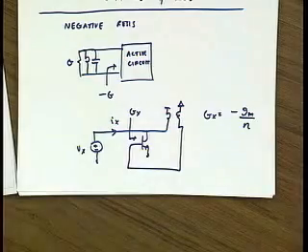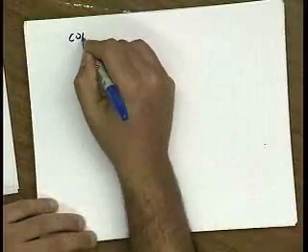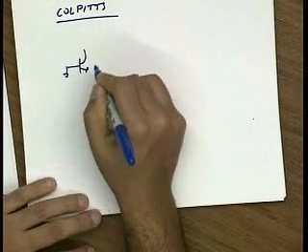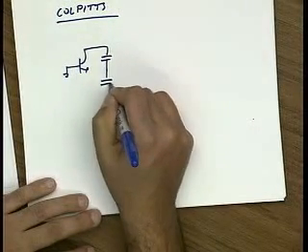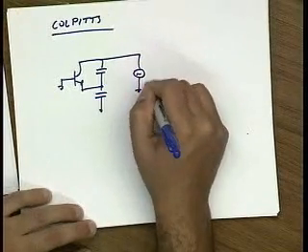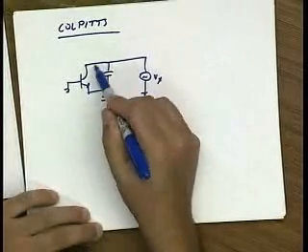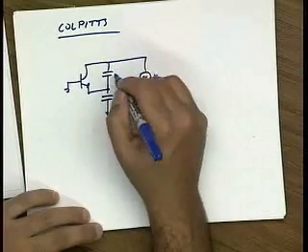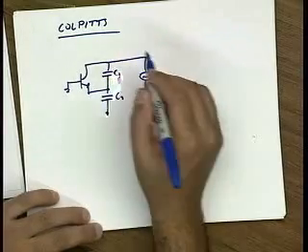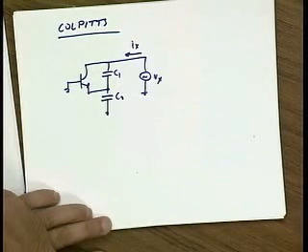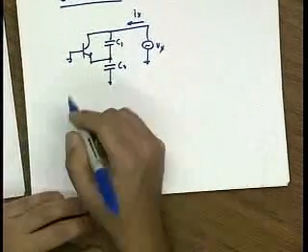All right. Now, there are particular oscillators to look at, for instance, the Colpitts oscillator. The way we analyzed the Colpitts oscillator last lecture is we noted that it's a common base oscillator, and therefore, to apply positive feedback, you can use a cap divider because you don't need any inversion. So the question is, from a negative resistance perspective, if I look into these terminals here and calculate this current, that should correspond to a negative resistance. Okay, so let me do that.